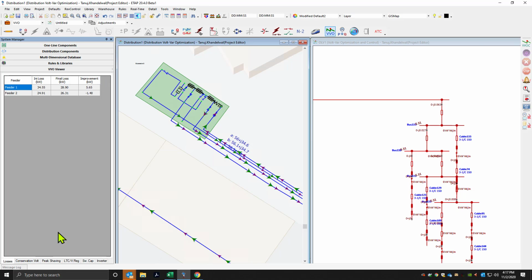So therefore the improvement may not be significant, but the CVR itself gives us the story where the lowest possible voltage on the node is 99.25%, and that the program has managed to bring it down to 95.01. So again, this is the lowest voltage found on that entire feeder, which has been reduced by about 4.25% to reach that minimum value. So this requires again a system level coordinated control to hit that objective and not have any node that violates that minimum voltage amount.